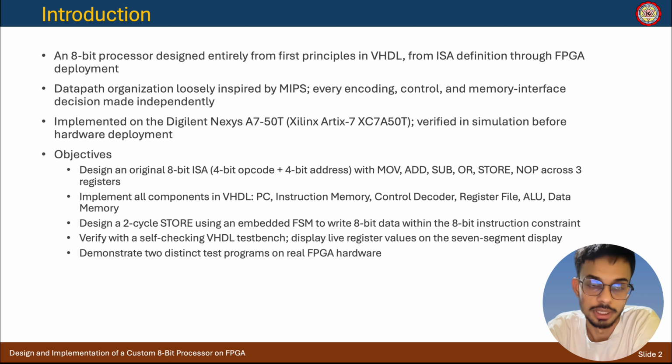Again, the introduction. It is an 8-bit processor designed entirely in VHDL, in which 4 bits are the opcode and 4 bits are the address, with 6 instructions: move, add, subtract, or, store, and NOP, and there are 3 registers. All the components are implemented in VHDL.